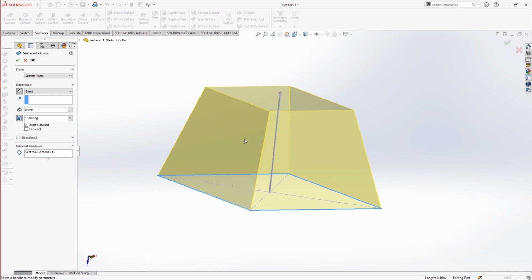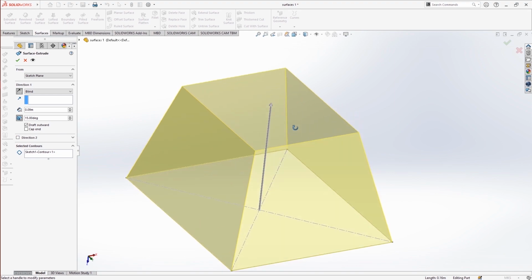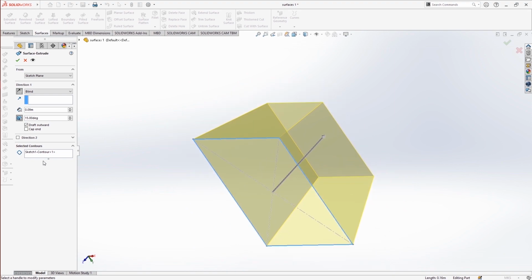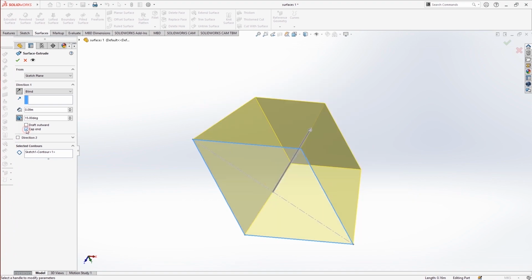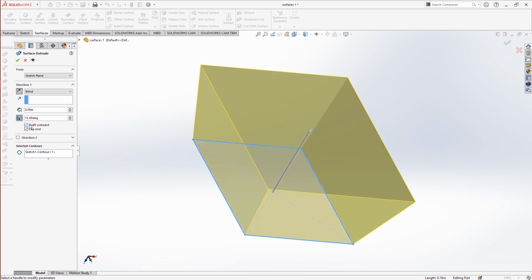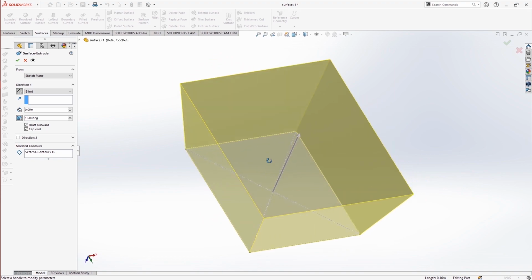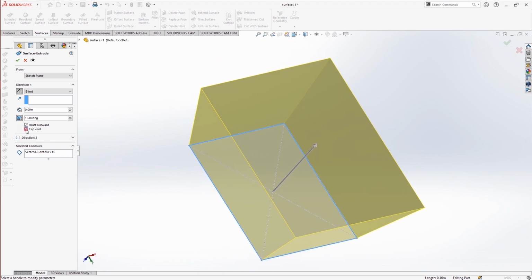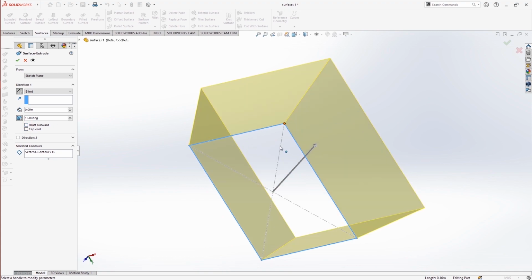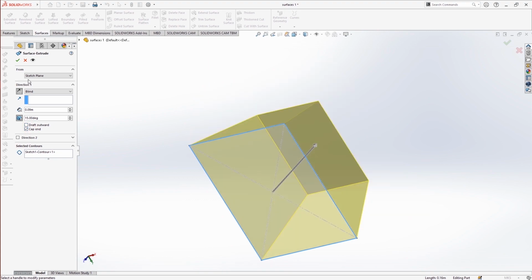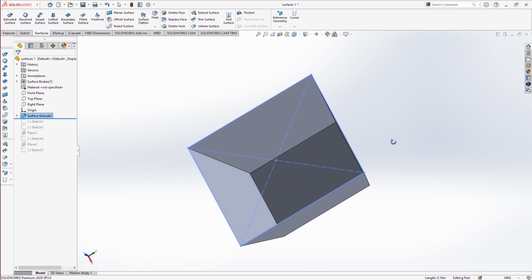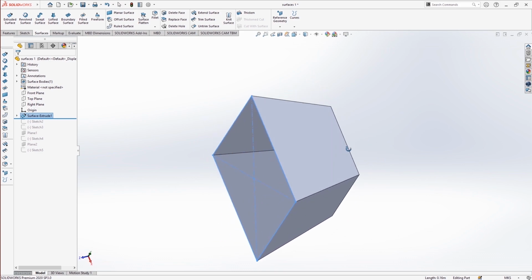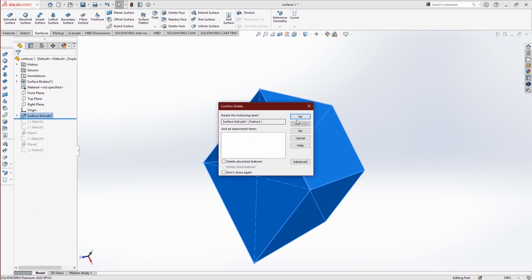Basically all of these things are like solid extrusion, and one thing that you will find different here is the option to cap the end, that is, to close the end of the surface. Look, it's closed. Here you can see this particular surface is closed, and when I click it back, it's unclosed. I will keep it closed and just press enter. Now you have a surface of a box. This is how you make an extrusion. Let's figure out other options. I will be deleting it.